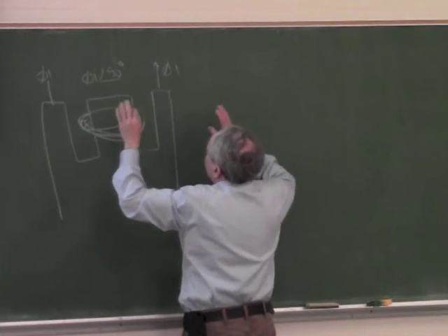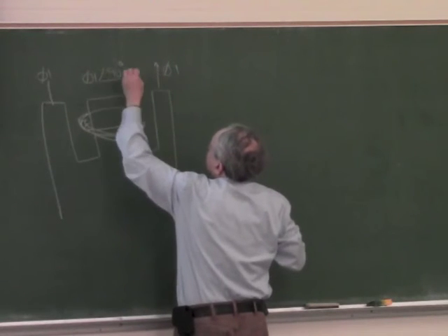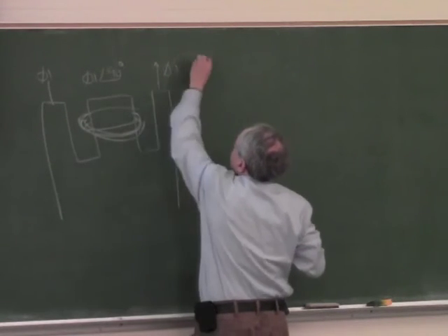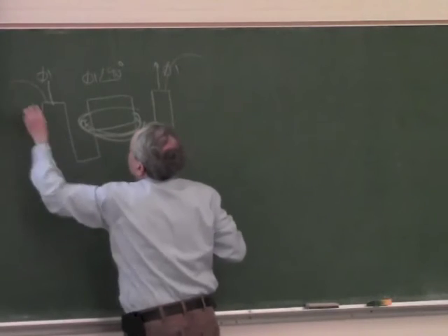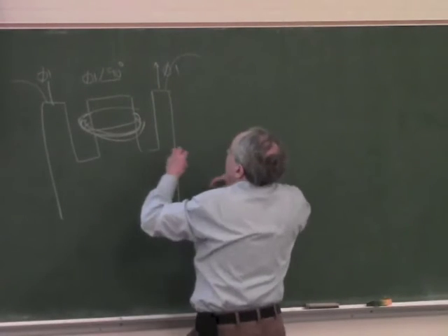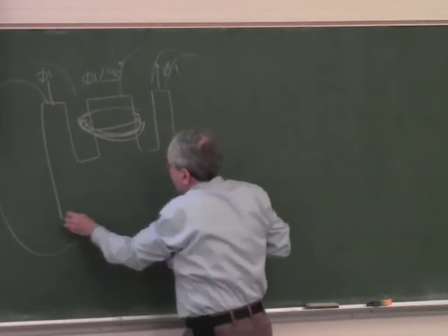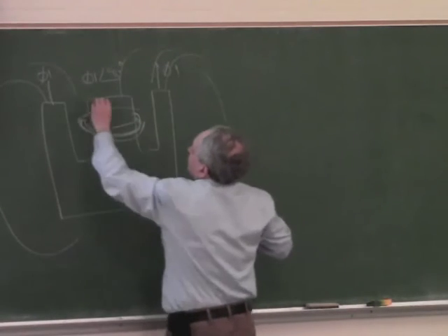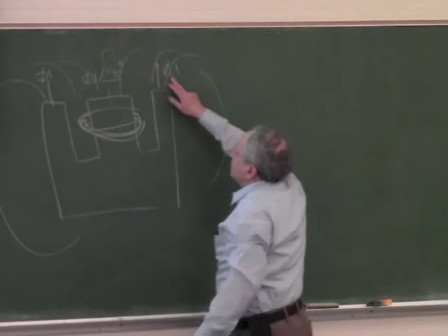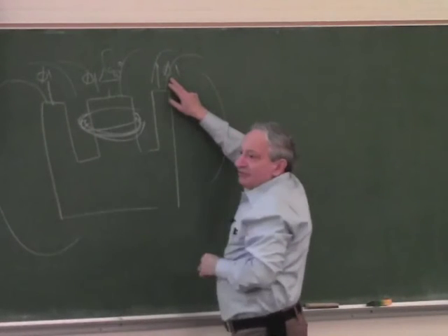Let's not talk about the coils. The field wants to go like this. It's hard to calculate where the field wants to go because these are at 90 degrees. But let's say the field is normal and wants to go back, connect to the other side. But the middle flux is 90 degrees away from this flux, so in between here there will be a rotating field.